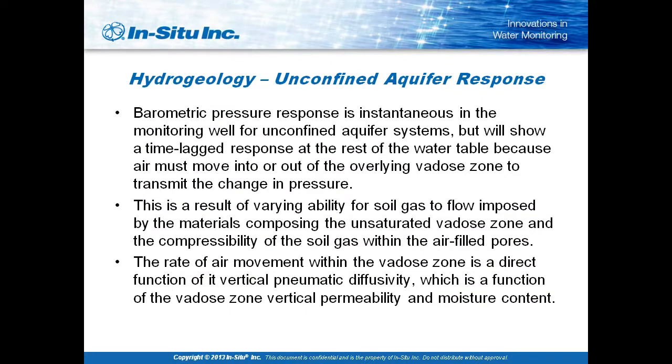Whereas in an unconfined aquifer, the response in the well itself is much less pronounced because the surrounding aquifer is affected in the same relationship as the well is. A way I like to look at it is if I put a straw in a glass of water and I blow on that straw, it's going to be instantaneous in terms of the effect around it. If I take the straw and I just blow on the glass of water, virtually nothing happens. So that's a nice way of looking at it. It all depends on the surrounding vadose zone and how permeable that particular vadose zone is.